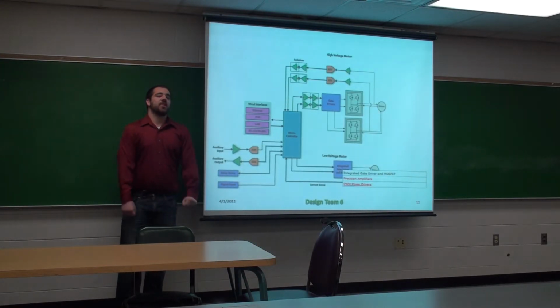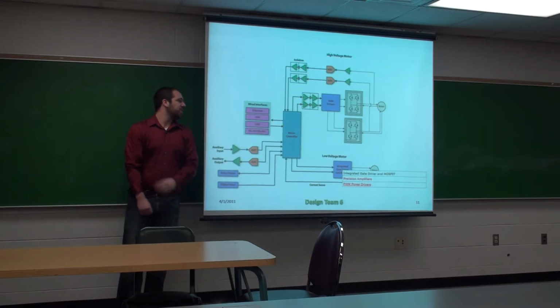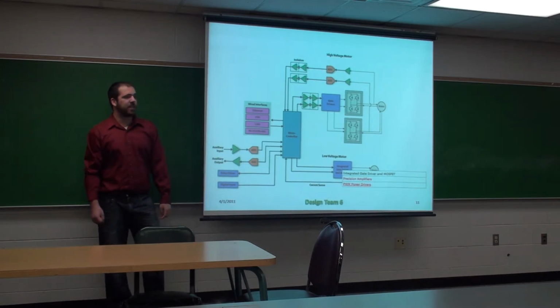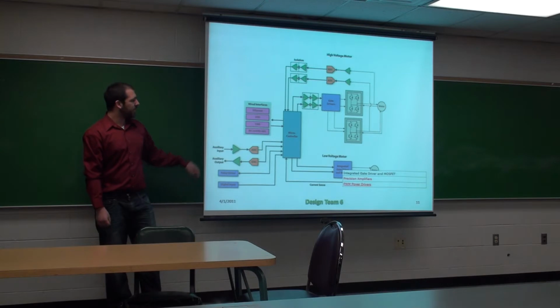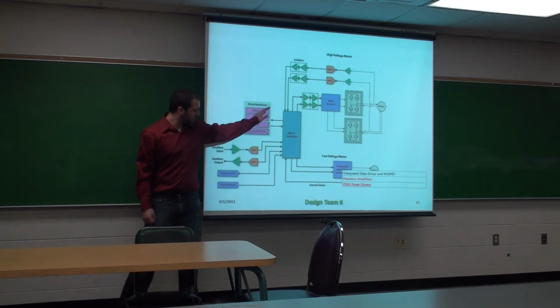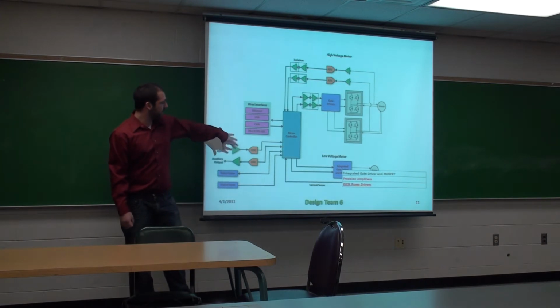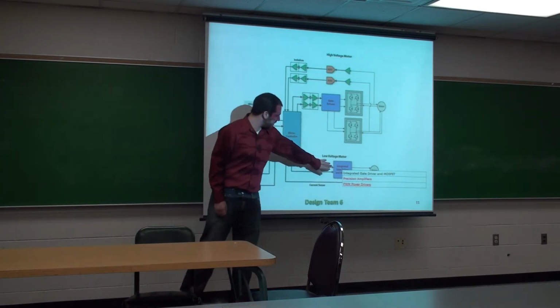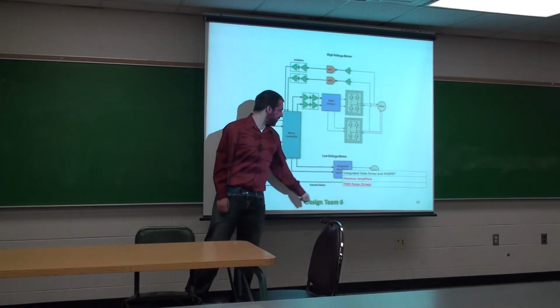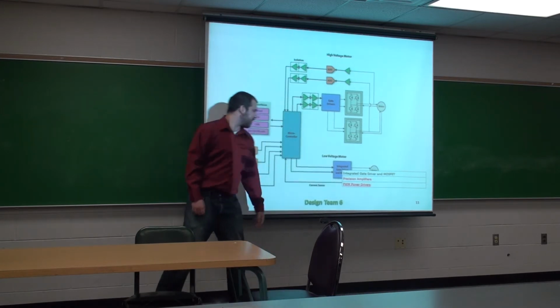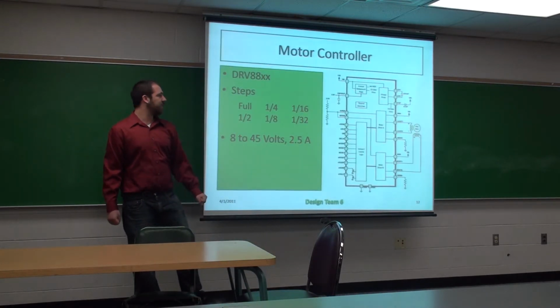So we wanted to decide which kind of motor controller we're going to use. How we do this, if you go on TI's site, you can go to applications. They'll bring up a schematic like this. They'll show you how to run low voltage and high voltage motors. This is just the microcontroller stage, but what we want right here is the motor driver, which will be in the low voltage motor. Click on it, click PWM drivers, and we'll come up with this.